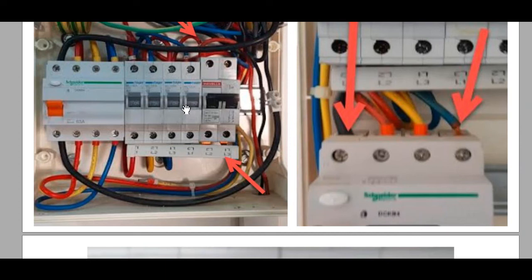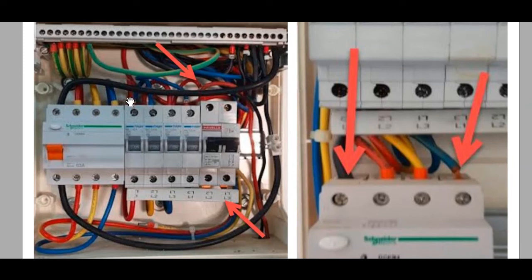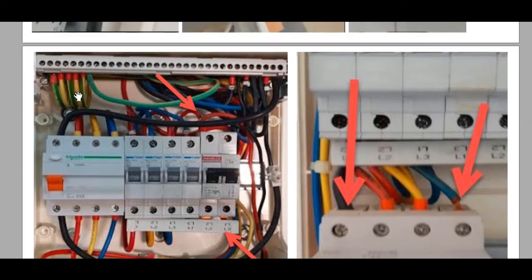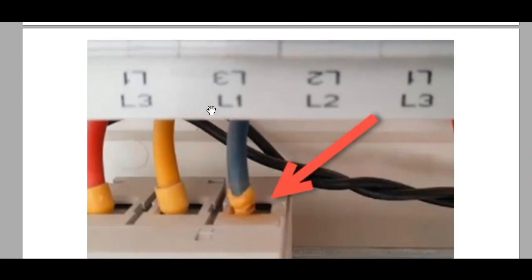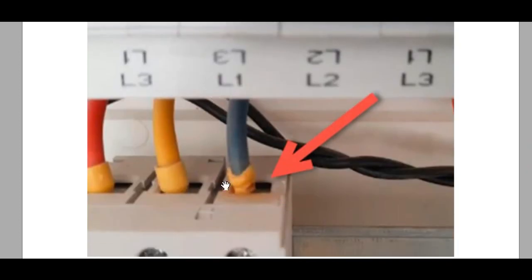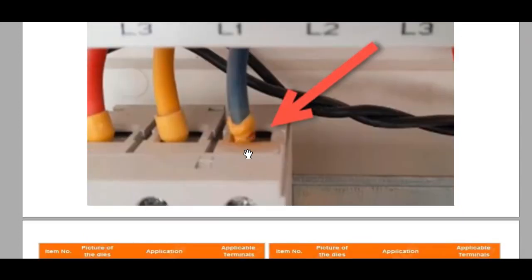So therefore this also makes it a big dangerous punch list. As you see here, for all the wires, there is no numbering. Some wires have numbering, the others have no numbering. And you see here, also here we have a bad connection, because two wires are installed in this circuit breaker without using the bootlace ferrules. As you see here also, we have a melted wire. It's very clear regarding this issue.